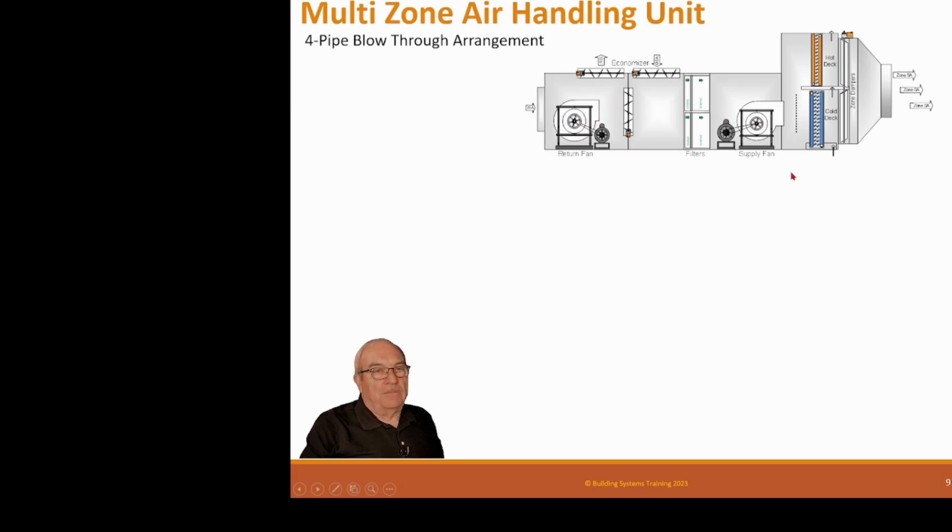Now, one thing I didn't mention on the dual duct, you notice this little dash line right here? This is called a blast plate. So when this air is blowing out of this air blower, it's high velocity, and this blast plate is just a plate with a bunch of holes in it, and it's designed to break this up, force some air up to the hot water coil and air around this coil, so that this coil isn't impacted with a high jet velocity.